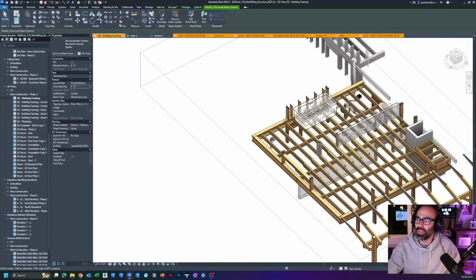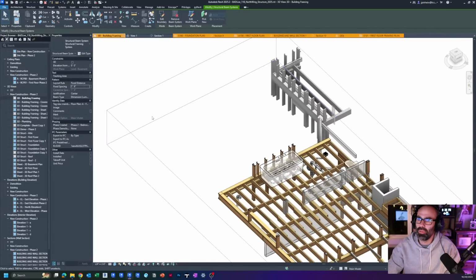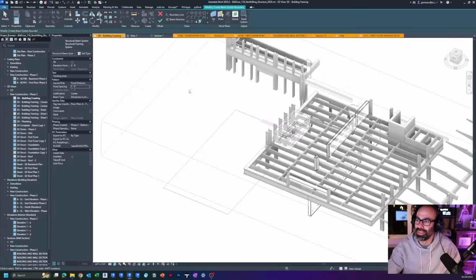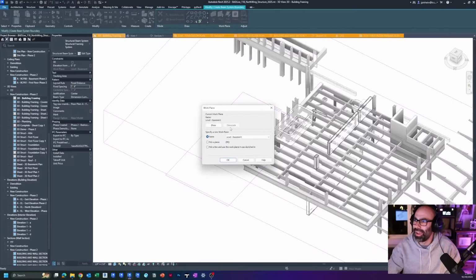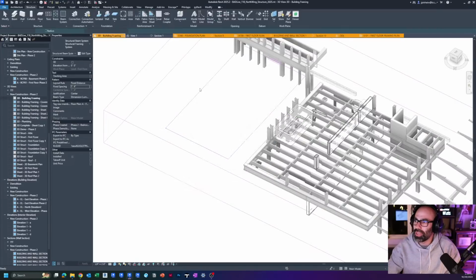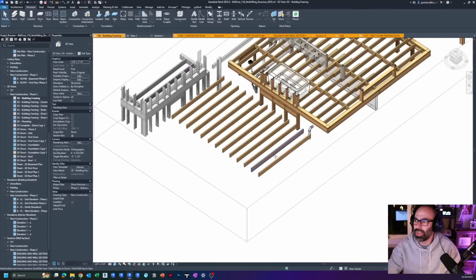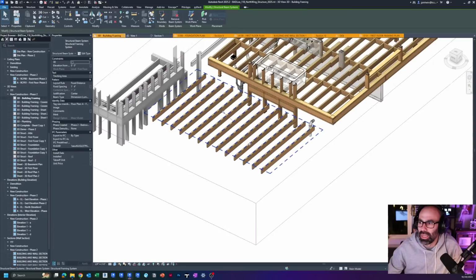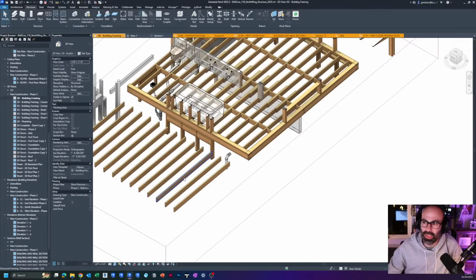And then, of course, I didn't have those on the right working plane. So let's try that again. I had those set to the basement. So let me set those to first floor and click finish. And you can see here's our beam systems. And so ideally you want to maintain the system as long as humanly possible. But you can also break away from the system as well.